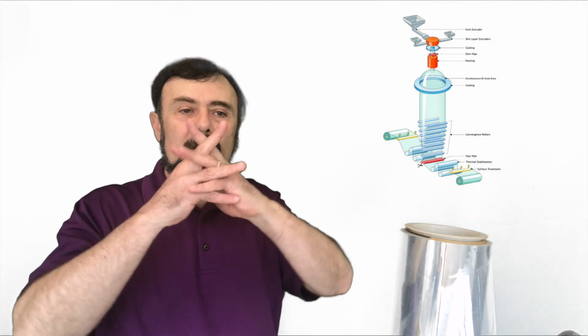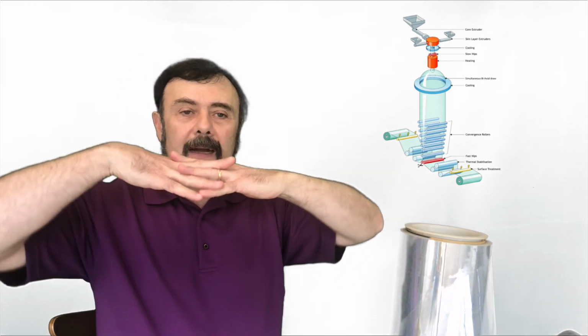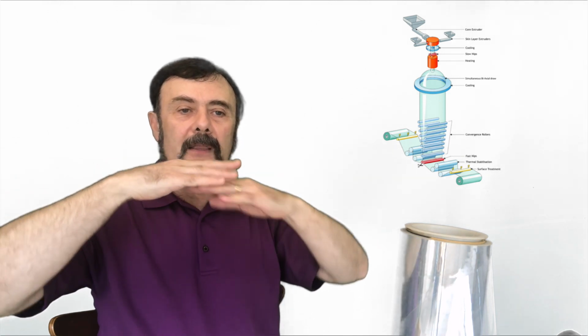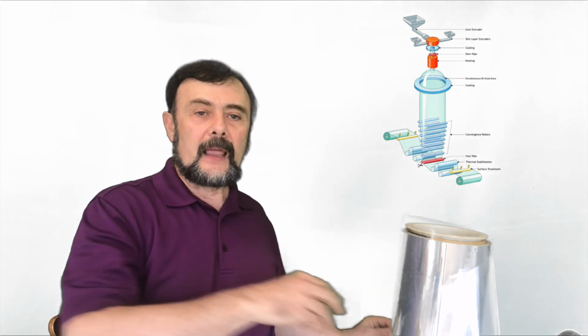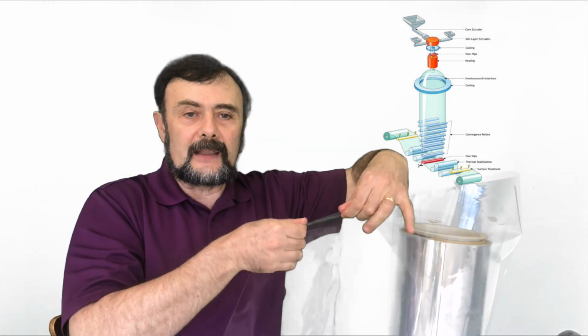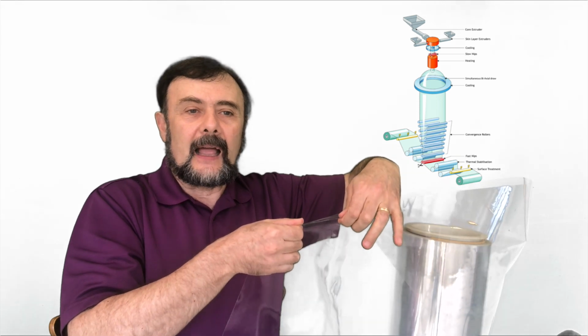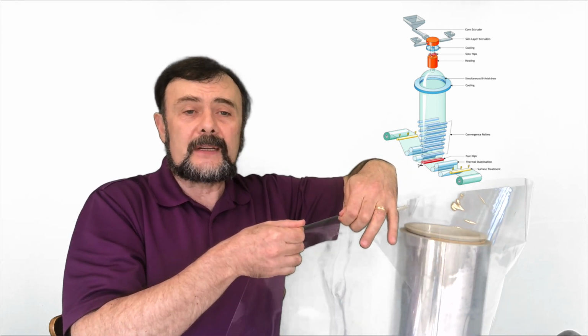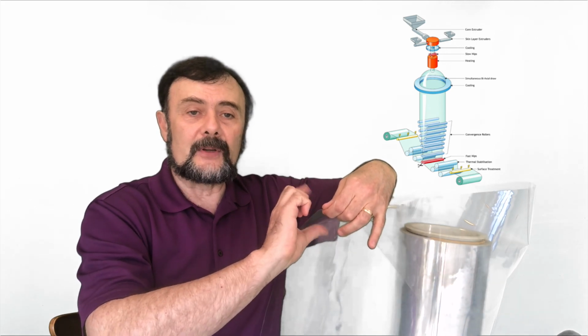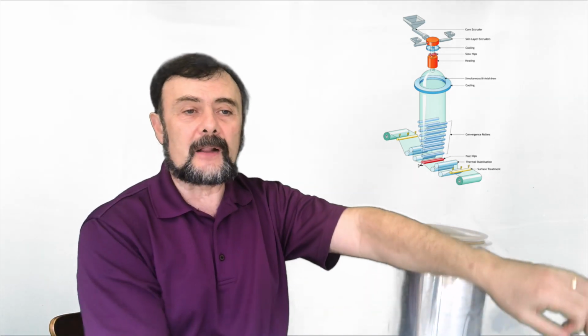The molecules that used to be randomly oriented are all lined up in one plane, the plane of the plastic film. This meant that the two axes of the film had a 30,000 psi tensile strength, as strong as a low-carbon steel, but the plastic film was very weak in the third axis, the thickness of the film, because very few of the molecules were oriented in that direction.